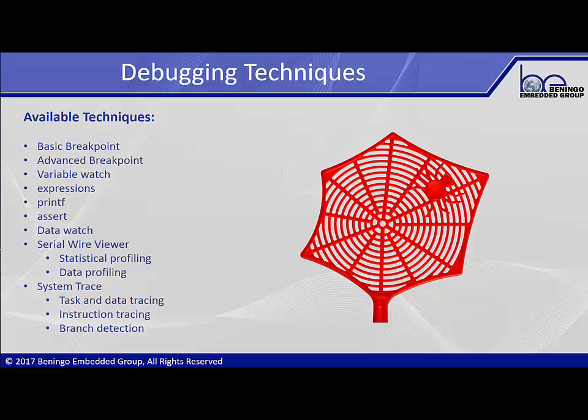The technique that we're going to be talking about probably the most today is actually going to be system tracing. And this is where we're setting up using a serial wire debugger actually, and we're just streaming trace data. So events that happen in the system, we're going to stream out of the system. So this could be when a task is initialized, when a task starts executing, when a task becomes ready to execute. Maybe there's data that we want to be able to send out. We can do that as well. So that's an example of the type of tracing we're going to be looking at today. Maybe when a semaphore is acquired or when it's given back. Those are going to be the system type of events that we're going to be looking at. Or maybe even if memory is being allocated from the heap.